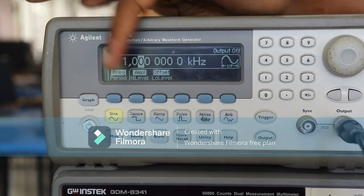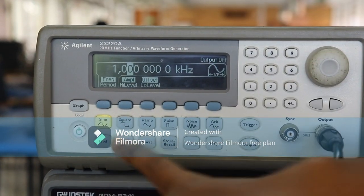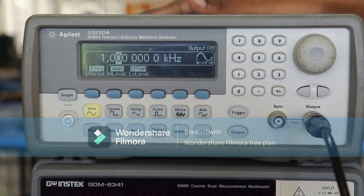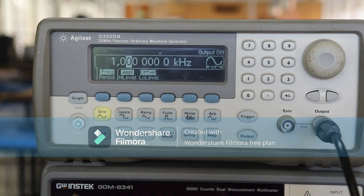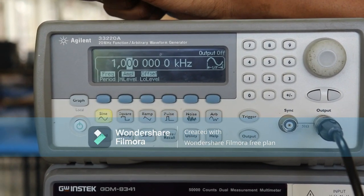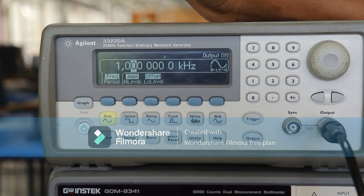Now, for this machine, we have a wide range of signals that we can select, which include our sine wave, square wave, ramp wave, pulse wave, and maybe also a noise wave, but you guys don't have to worry about that for now. We're just going to start off by using our sine generator. We press the sine button, and we'll first look at how to set the frequency. That should be the first thing that pops up on the screen.